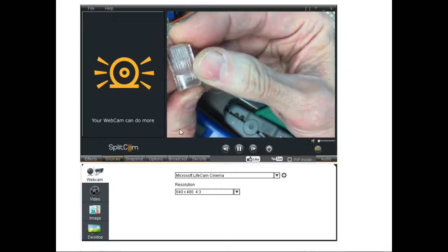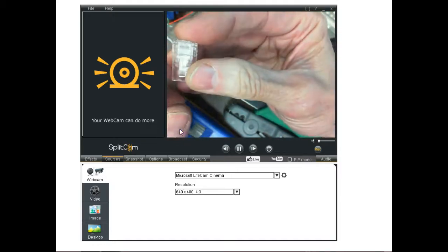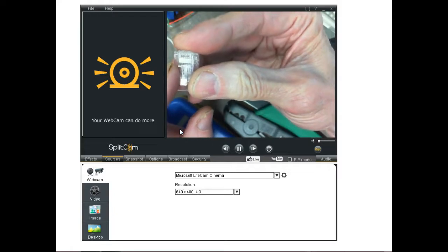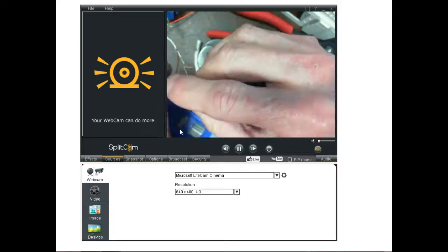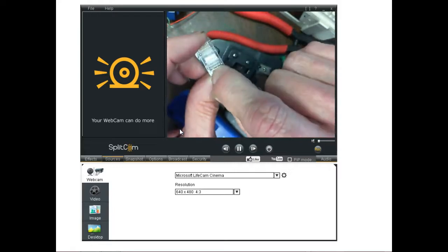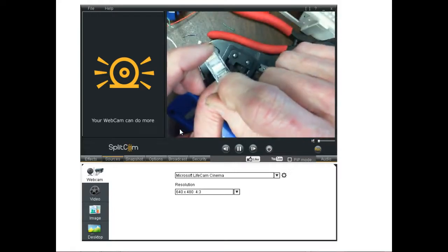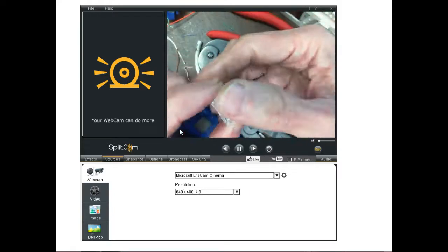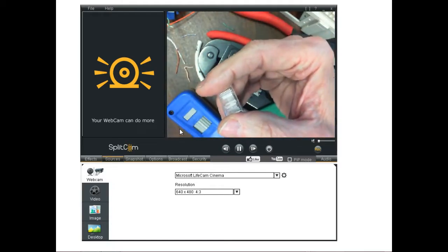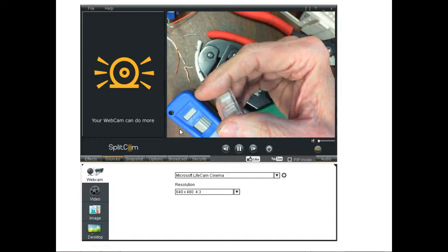The problem we have is people will jam them in like this, and they'll do the right color code, but it's just exactly backwards. Then we'll have people, they'll crimp it, and they don't get their insulator where? Under the crimp for the insulator. And then when you do that, then the crimps out there on your wires are the only thing it's giving you not only your electrical, but it's doing your mechanical too, right?